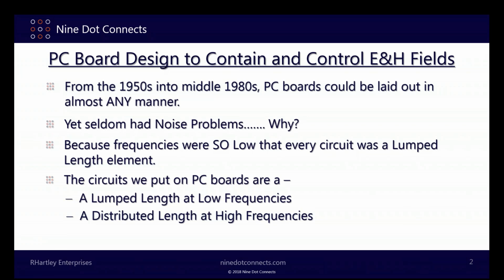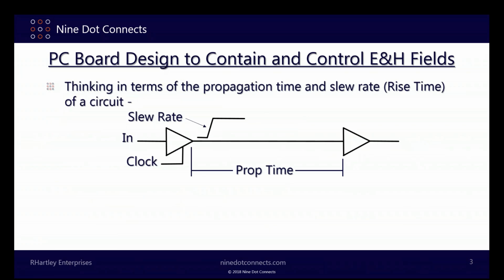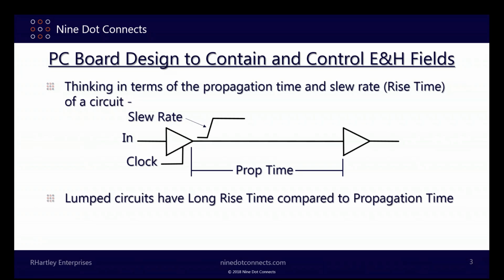They're now basically distributed. Thinking in terms of propagation time and rise time, or slew rate, however you choose to look at it, basically circuits are lumped if they have a long rise time compared to propagation time.